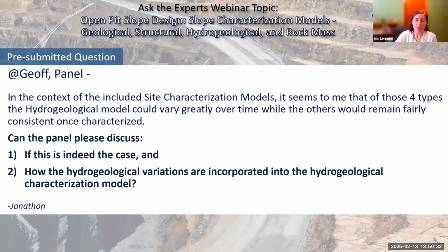In addition to that, weathering becomes an issue on the scale of how long a pit is operational as well. Rocks that were covered initially, once they're exposed to air and water, can in some cases change relatively quickly, and the weathering will change in the time scale of how long that pit is operational. Yeah, that's a really good point. Yeah, it's also the stress release as well for some rock mass units can be quite influential on how it will behave.